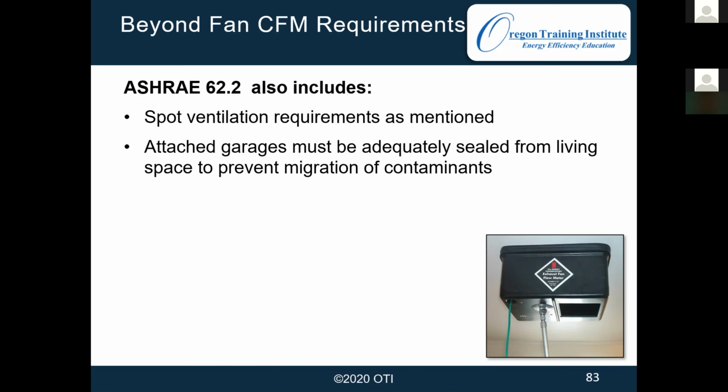Any obvious penetrations need to be sealed, including, if necessary, weatherizing the door, weather stripping it, but also any penetrations sealed around the wall between the house and the garage, where that's framed, like at the bottom of the wall plate, or drywall in the garage might have some gaps that might need to be sealed, as well as any penetrations.